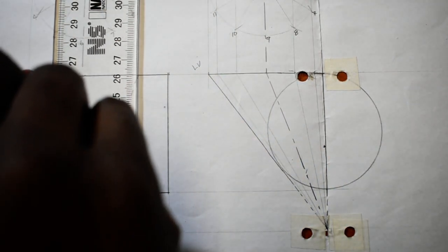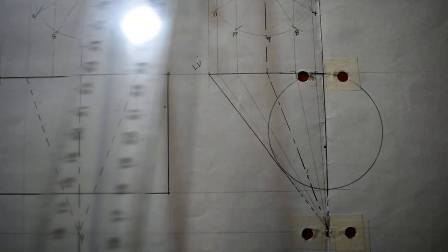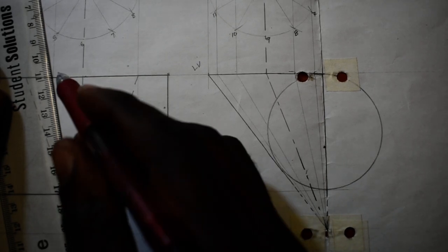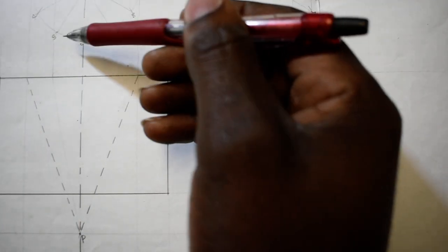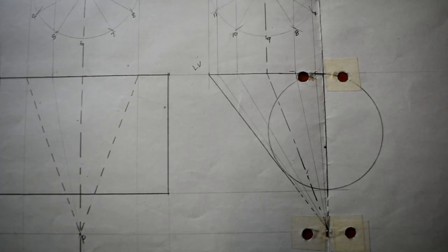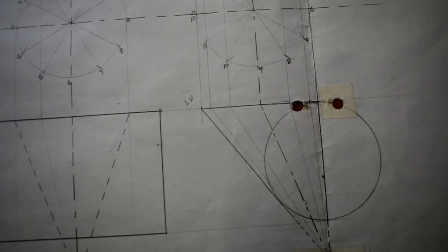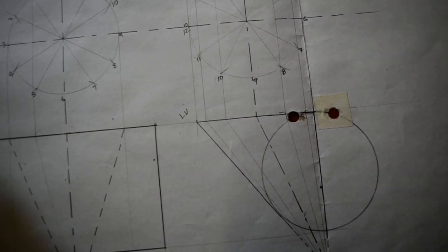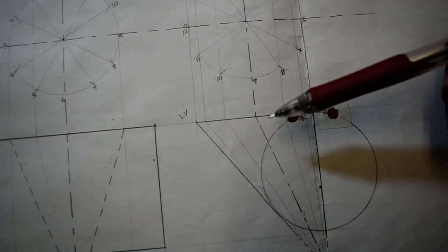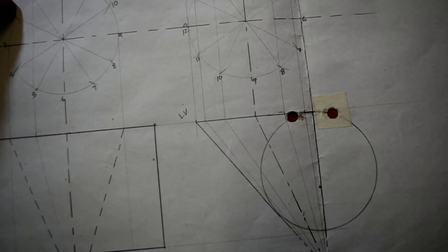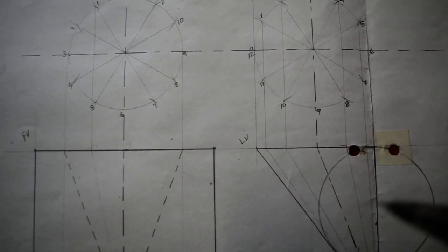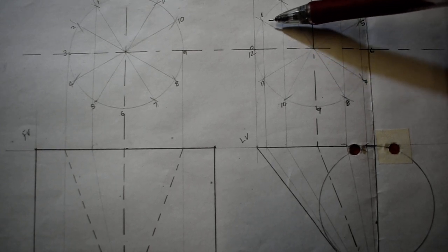There it goes. Once it touches here, go back, go down to your apex point. So this is point 1 in line with what? With point 5. You understand? Remember, this is your front view. So what we know is that the point 1 of our auxiliary left must intersect with the point 1 of the auxiliary front view. You understand? So let's trace the point 1 of the auxiliary left view.